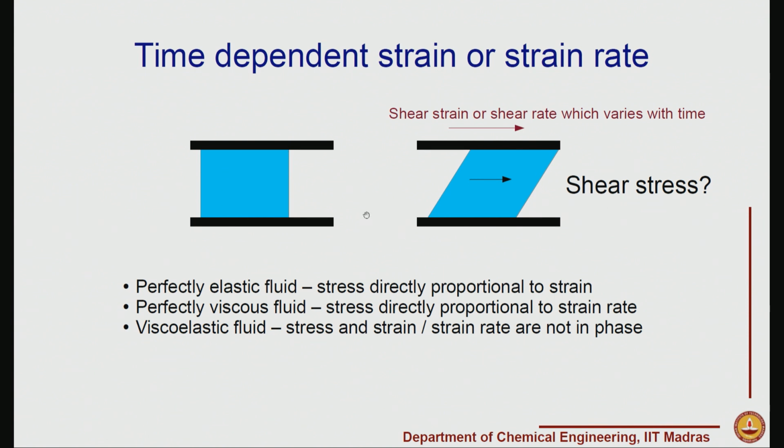So, again going back to the colloidal system that we thought of, where there were clusters and networks of clusters, what we can see is when we shear the system continuously in time, the clusters also get adjusted based on the deformation being imposed. Therefore, the overall property of the fluid that we observe will depend on the magnitude of the shear strain amplitude or of the shear rate which is being imposed.